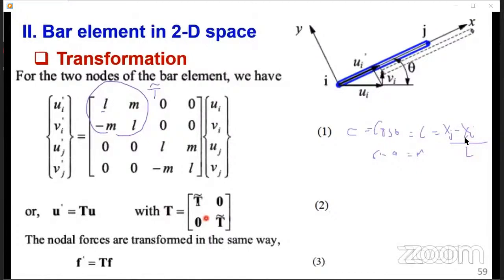Okay. So if you want to get the force in the global coordinate system, we have it in the local coordinate system at the elemental scale. You just need to pre-multiply the global quantity with the transformation matrix. And remember, I know you know this, the order of matrix operation is very important. This T being here is not the same as the T being after F.